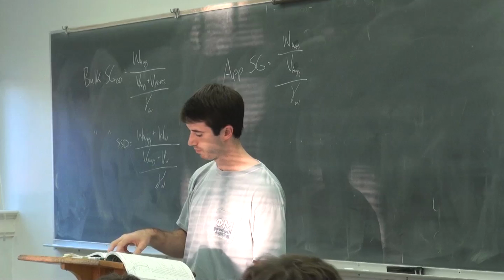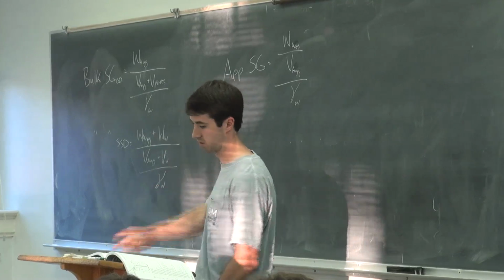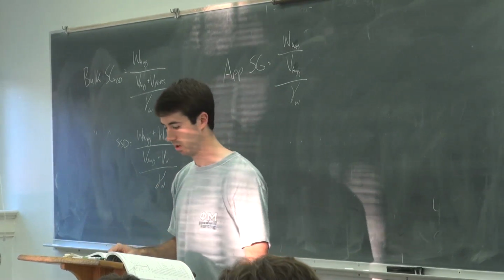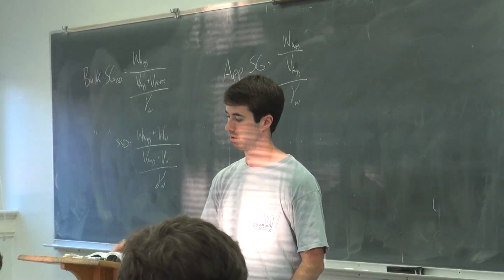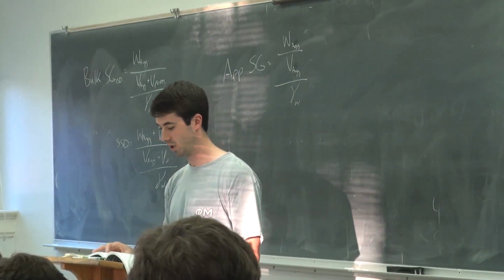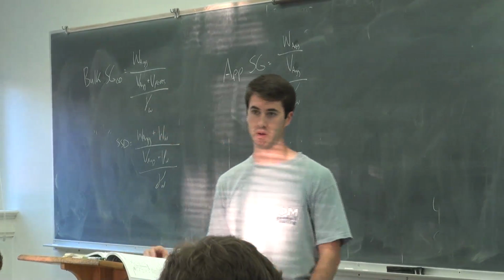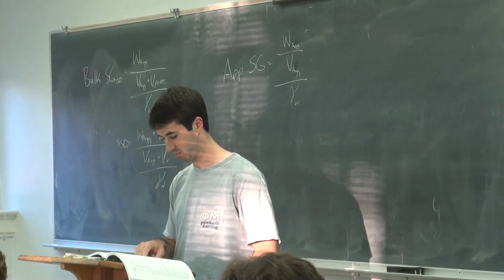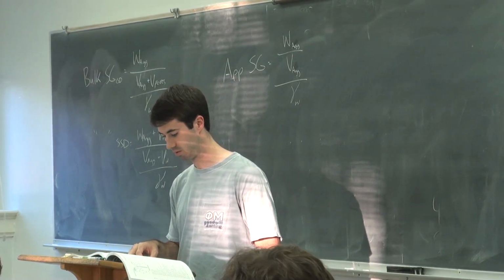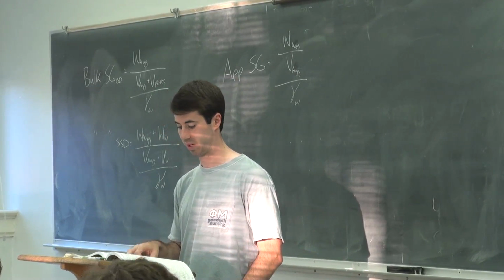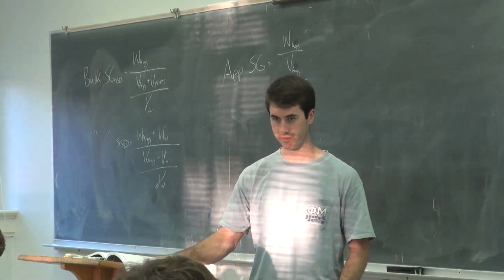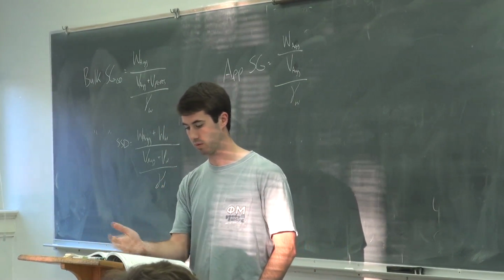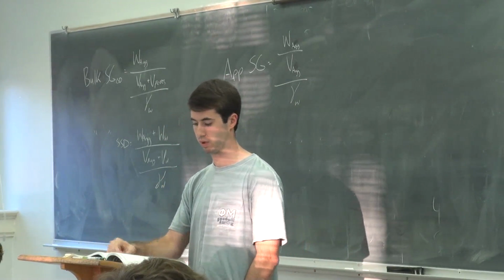You've got different aggregate states. You've got oven dry, which would be that case. You've got SSD, which means the pores are full of water, but no more. You've got in between, which is typically air dry. And then you've got damp or wet, where you've got too much water in there. You can see on there, total moisture would be the weight minus the weight of oven dry, divided by the weight of the oven dry, times 100. And then you've got absorption, and you've got surface moisture, which would be the total minus the absorption.